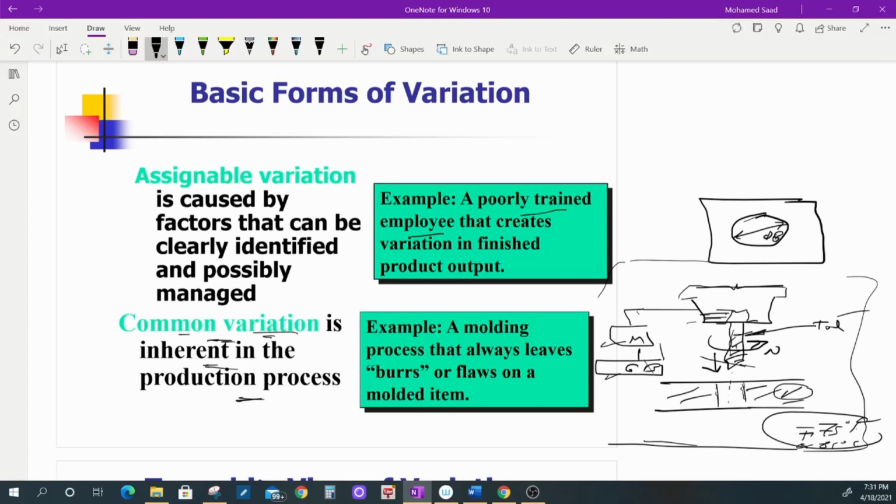The same for the gearbox: if I get a new gearbox, it will help reduce the vibration. If I make sure the tool material and tolerances on the tool are really high grade, that I can depend on, and if I control the temperature, these can be improved, but again they can't be eliminated. You can't really eliminate the motor or the gearbox or the tool or the part. I mean, then you would have eliminated the process.